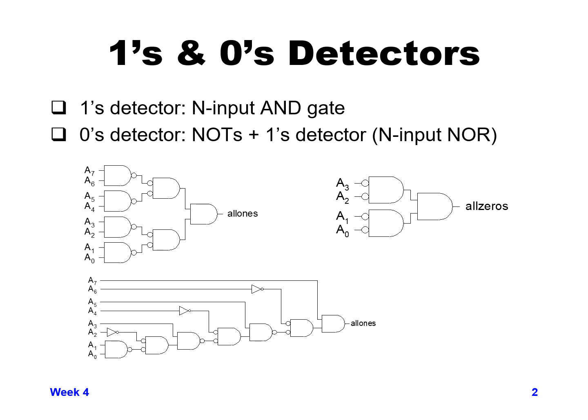So the bubble of the NAND gate and the not AND gate cancel each other out, and so you get an AND function out of that. The not AND gate, due to De Morgan's theorem, is basically a NOR gate. So if you do a NAND gate followed by a NOR gate followed by a NAND gate, you effectively get an AND function out of that.